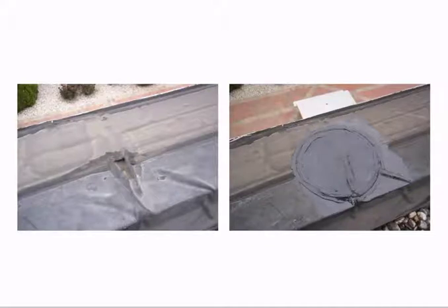And then you're putting your stripping on, and you're rolling your stripping in with your neoprene roller, with the correct pounds per square inch on that. Well, over time, that stripping will shrink, and that's what happened here. It shrunk, and it looks like it popped up out of that corner. And job well done on the repair patch for that. A nice round, we call that a T-patch, over that situation there. So that's a long-term repair.